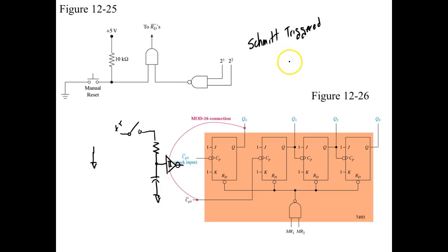The problem we have with a standard TTL gate without the symbol in it is that this one can recognize anything around 2 volts as a legal high, and around 800 millivolts as a legal low. Now this one usually guarantees around 2.4 volts as a legal high.